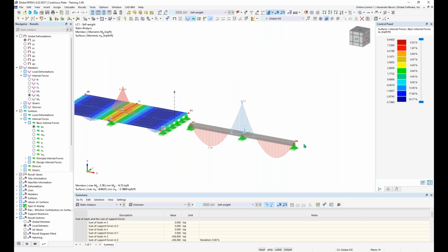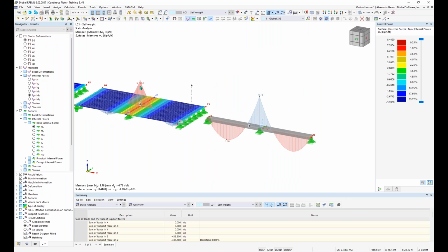and now we can see how the results deviate from our previous results. So now you can see something like our member bending moments have now increased to 7.2. Before they were closer to 7.0. And so that is what happens when you take into account or don't take into account shear stiffness. And this is the results you should see if you're doing hand calculations.